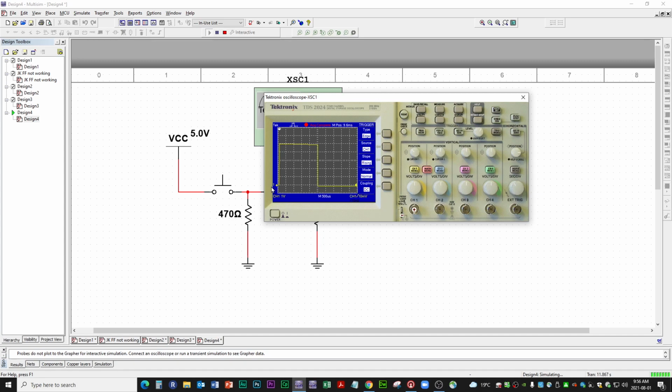All right, now here's our 0 reference, that's where we set it, and the pulse was being captured from the beginning of the screen. So we can still position it left or right, just so it aligns with the grid on the screen, so it's going to be easier for us to measure things. All right, so channel 1 shows 1 volt per division. Here's our 0 reference. See how high our pulse is, how tall. 1, 2, 3, 4, and 5. Okay, so 5 volts. There you go.